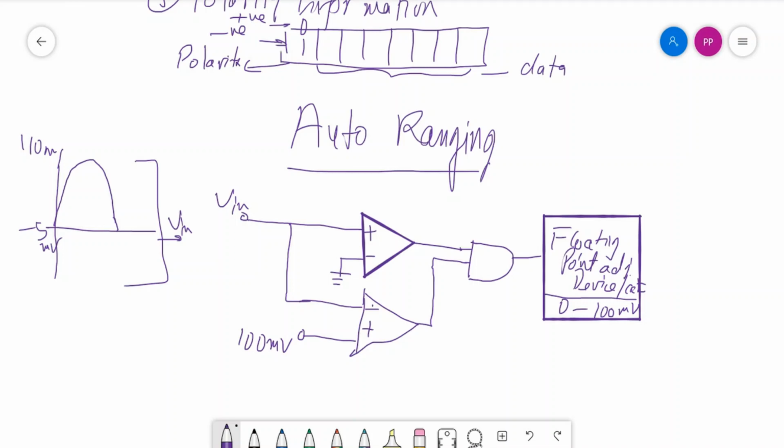Now every instant of the voltage is coming into the inputs of the comparators. As soon as it is below 0, suppose this voltage is 0, the output of the first comparator, I say first comparator, this is the second comparator, is negative, because 0 is ground and -5 millivolt is less than this, so this is 0.